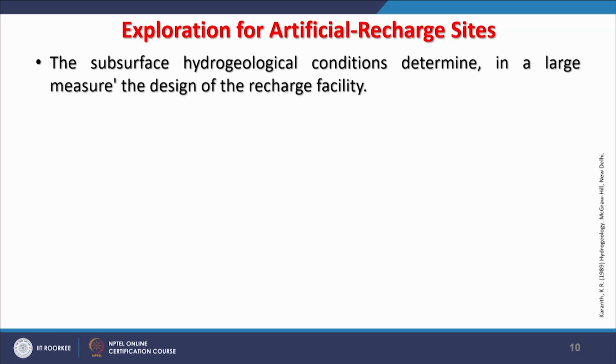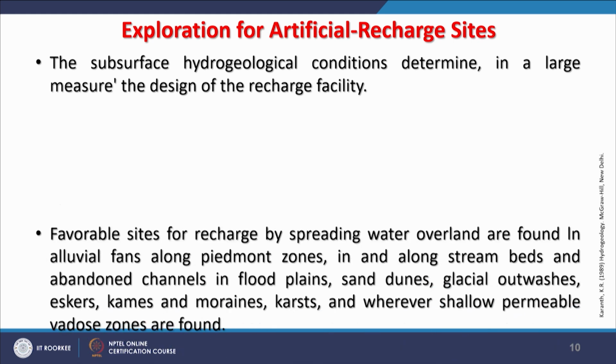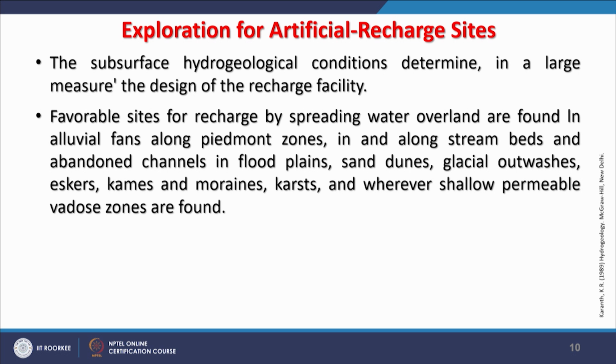So, while doing such exercises or development on the surface or in subsurface conditions, the quality of source water should be maintained, so that our groundwater remains safe. For that, subsurface hydrological condition determination is required in a large measure to design these groundwater recharge facilities, and favorable sites for recharge by spreading water, that means on the surface.